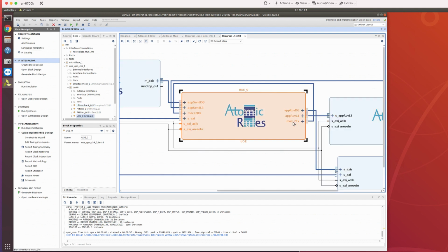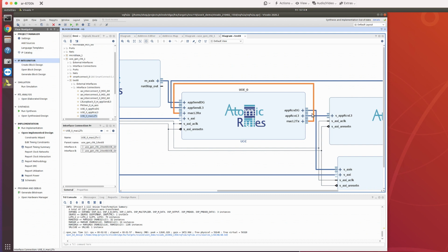You can see that there's a connection from the MAC TX that we're connecting right back around to the MAC RX. So in this example, the datagram generators are generating datagrams. They're converted into L2 frames. The L2 frames then come back in, and then the datagrams are checked. So we're going all the way through. This is similar to doing a MAC PCS or media loopback.